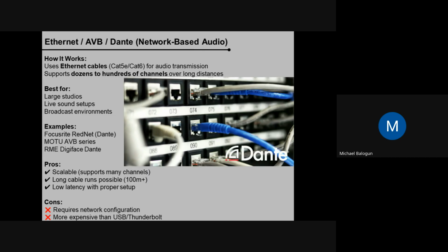We now introduce how we do our streaming, our IT. Back then it was a sound card that we used. We took output from the board, from the system upstairs, from the broadcast system. This thing does digital to analog, analog to digital. So output from the sound card, we now transmit it. We run the cable to the IT guys. They also have a sound card that they use to embed audio into their streaming.